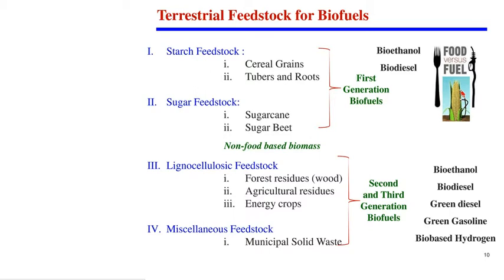We can use the subcritical hydrothermal carbonization process to make biochar, or we can liquefy biomass and then upgrade it catalytically to make liquid fuel, or gasify biomass and get Fischer-Tropsch. Through Fischer-Tropsch we can get liquid fuel, or make hydrogen or methane gas. So these are the three major routes: biochemical, thermochemical and hydrothermal. I am going to focus my talk on hydrothermal.